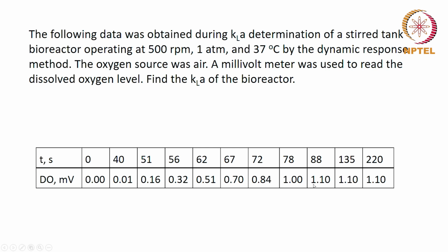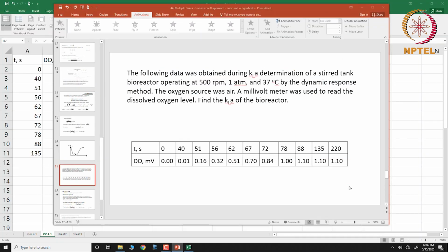The value in the gas phase that is in equilibrium with the bulk phase concentration in the liquid phase, right? So this is the value that you're looking for. So you have a measure of that itself, so you can directly use it. If you don't have a measure of that, you'll have to measure the saturated value and use that for C star. That's as simple as that.